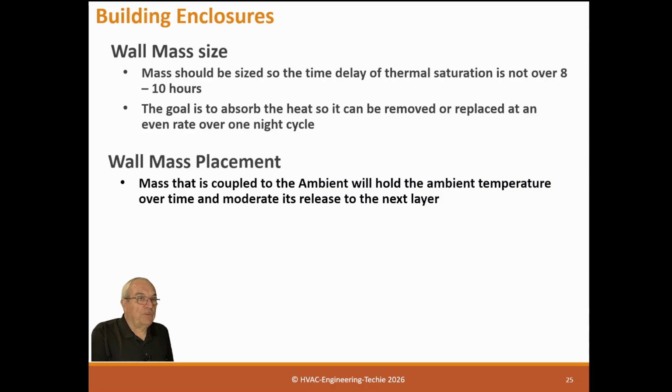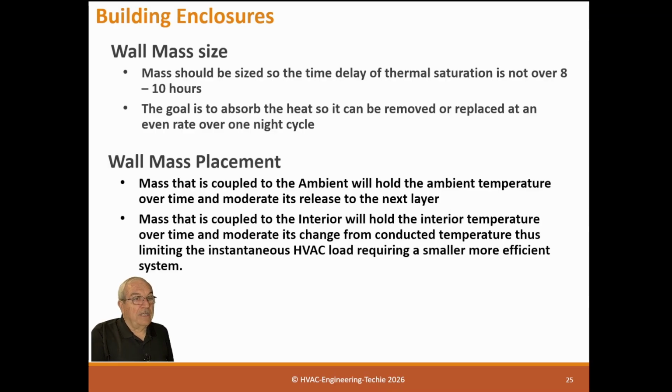Mass that is coupled to the ambient will hold the ambient temperature over time and moderate and release to the next layer. Mass that is coupled to the interior will hold the interior temperature over time and modulate its change from conducted temperature, thus limiting the instantaneous HVAC load, requiring a smaller, more efficient system. I've already said that, but that's true.